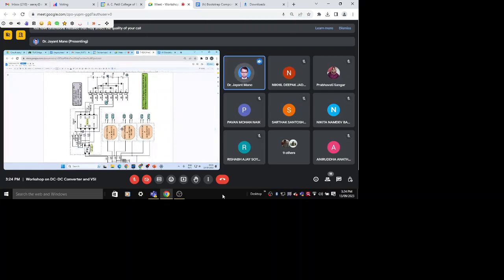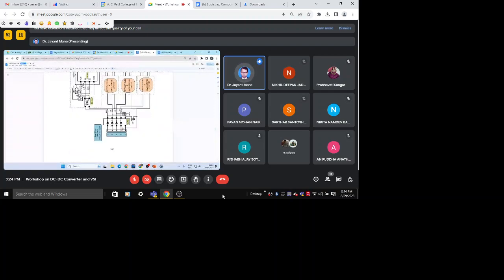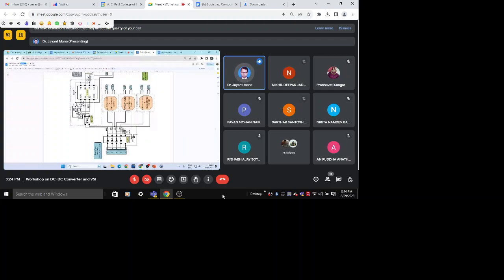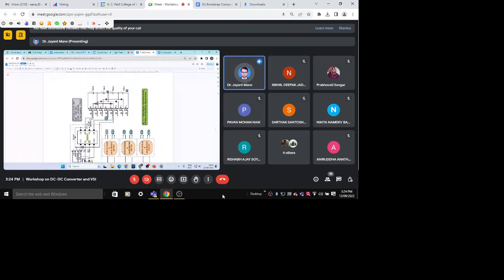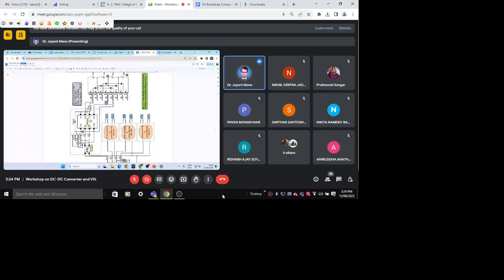This is a multi-level inverter. One leg of the inverter, 8 switches and 6 diodes in the DC bus. Through each driver I was driving two switches. I need at least four such drivers to drive all the eight switches of one leg.